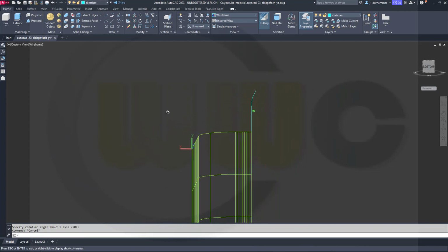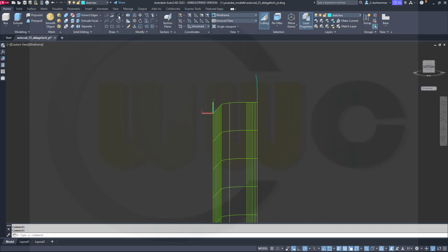And let's take a look. So that's again the start point, center, angle, arc. So the start point would be at 0, 0. The center should be at minus 50 column 0, and the arc should be maybe 120 degrees.